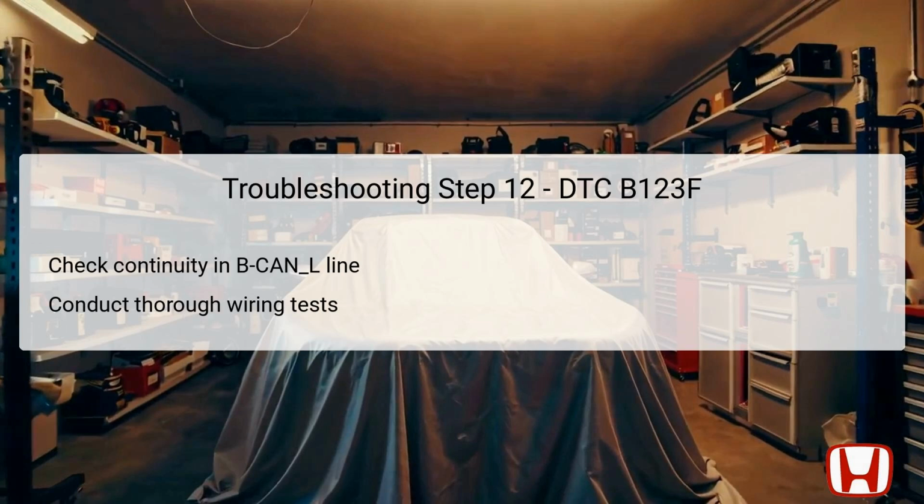Assess the continuity through a connection from test point 1, located on the automatic lighting control unit sensor 5P connector number 2, to test point 2 at climate control unit connector A, 32P number 8. It's essential to verify that the BCAN L wire is operational and intact. A successful continuity check confirms the wire is functioning correctly, while a failure indicates a need for repair to address any openings in the circuit that may be leading to communication issues.